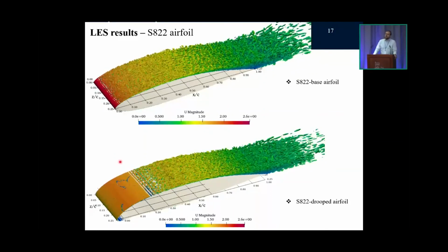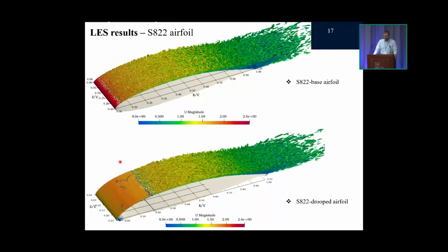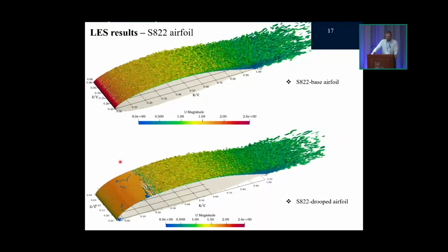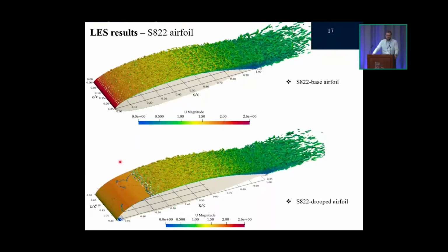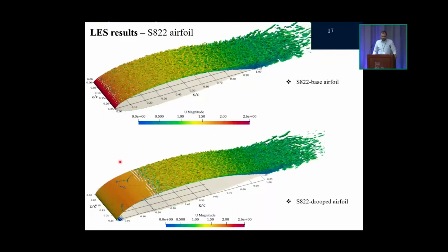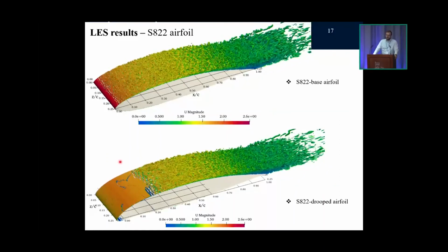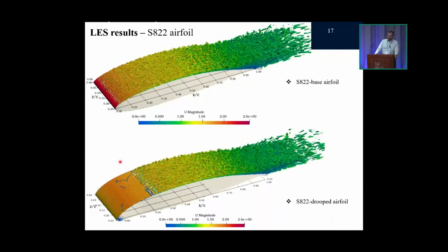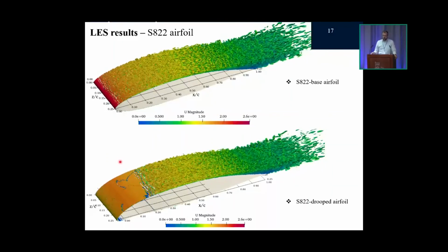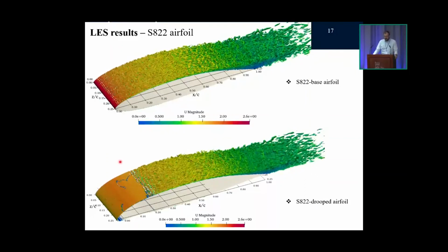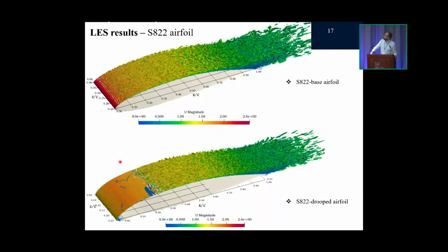We think that corresponds to an inviscid instability like a Kelvin-Helmholtz mode, which very quickly rolls up and becomes three-dimensional, and the amplification of disturbances in that laminar separation is quite strong, and thereby we have a rapid transition to turbulence that then continues and evolves as those structures begin to interact with one another and grow to a more fully developed turbulent boundary layer over the rest of the airfoil.